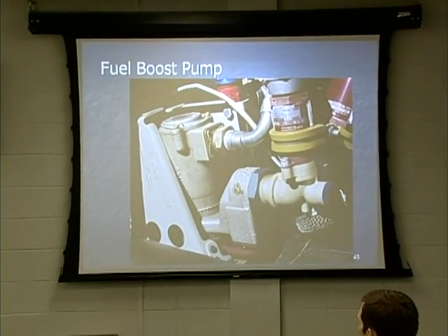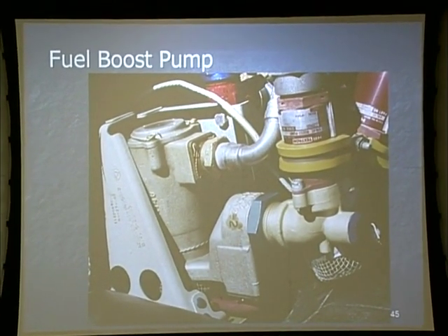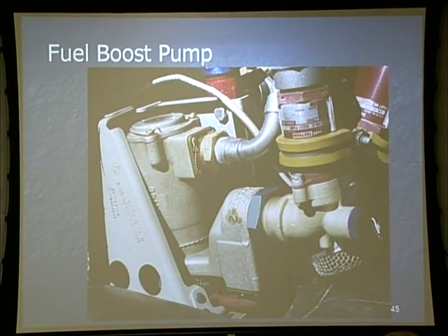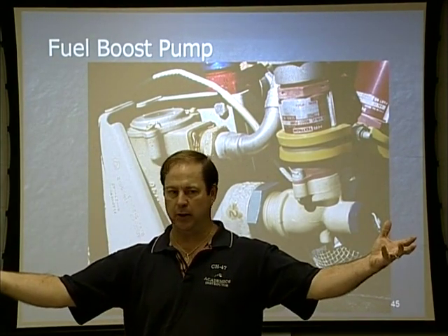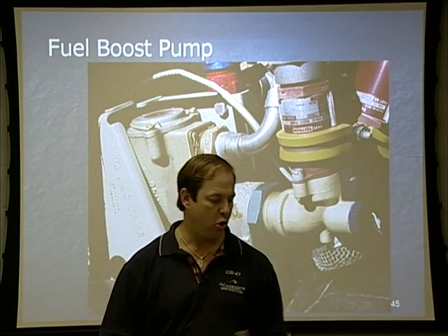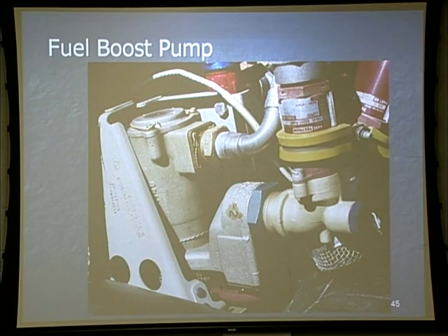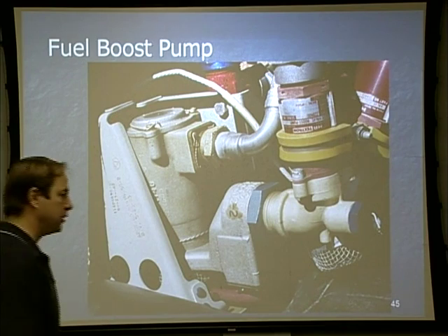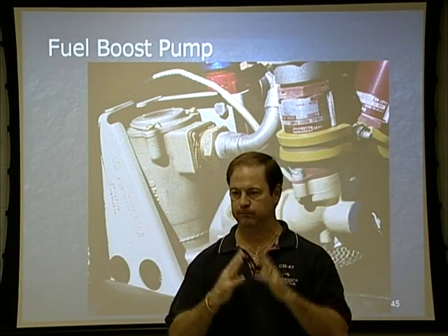Fuel boost pumps. 115/200 volts AC. We had electrical yesterday. Now it makes sense, right? DC controlled, AC operated. Normally, the left side is going to be powered up via the number 1 electrical system. The right side is going to be powered up via the number 2 electrical system. But keep in mind, we're not talking about with a bus tie or without a bus tie. We're just talking normally. That's how it's powered up.